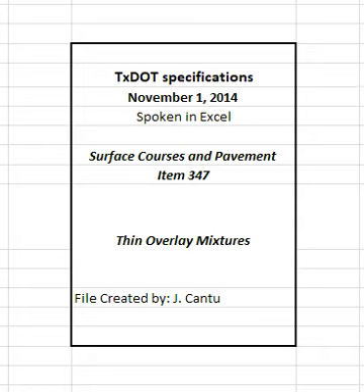4.4.2.1.2 Gyratory compactor correlation factors. Use TEX 206F, Part 2, to perform a gyratory compactor correlation when the engineer uses a different gyratory compactor. Apply the correlation factor to all subsequent production test results.